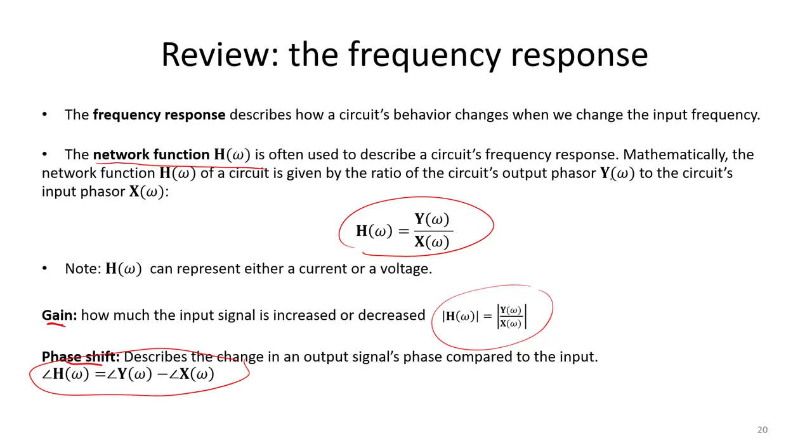Remember that typically it will be given in the question what the output and inputs of interest are. So to find frequency response, we typically just convert our circuit to frequency domain, and we derive an expression for the y and x terms as a function of omega.